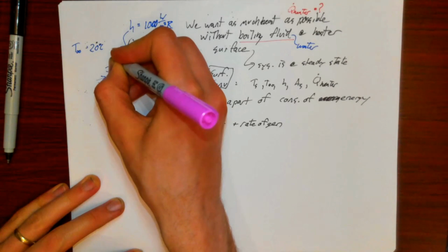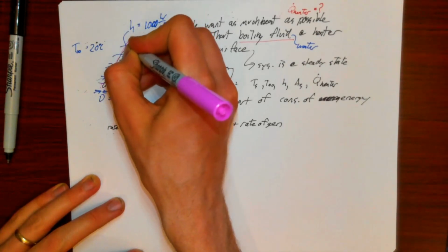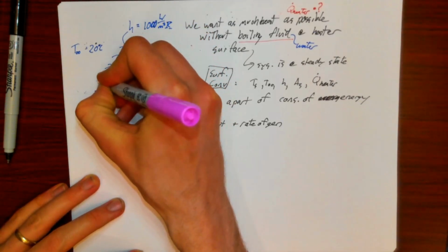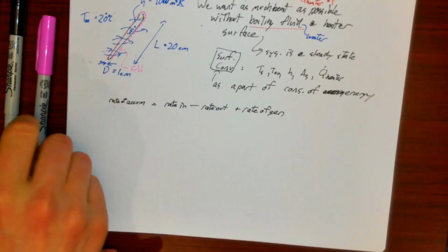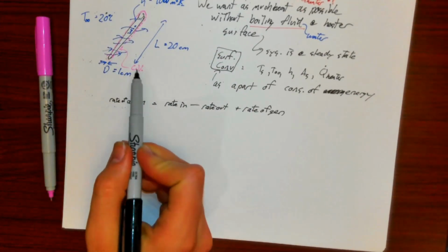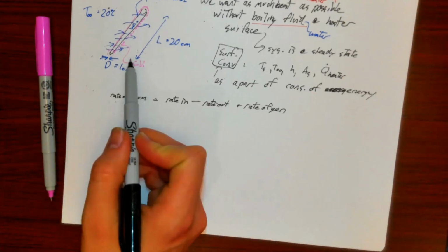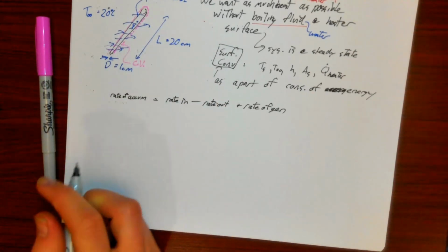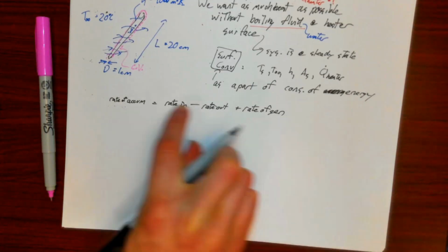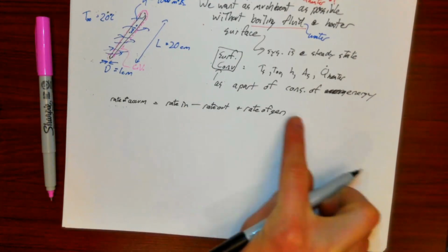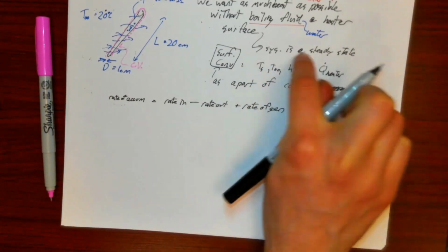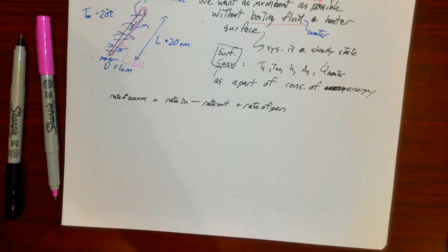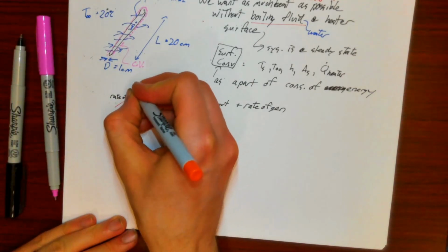So what is it going to look like? My control volume is basically just going to be just barely outside of the solid surface right here. So that's going to be my control volume, and I can apply conservation of energy to this control volume that I sketched out here. So let's think about various terms that we might be able to get rid of. Rate of accumulation: I said my system's operating in steady state, so I can get rid of my accumulation term because I'm steady.